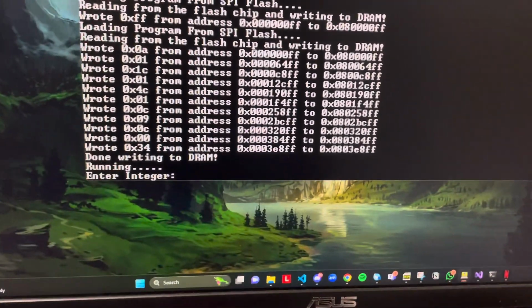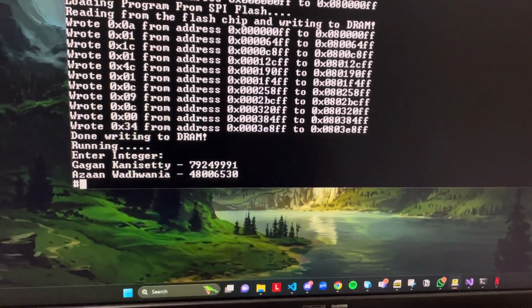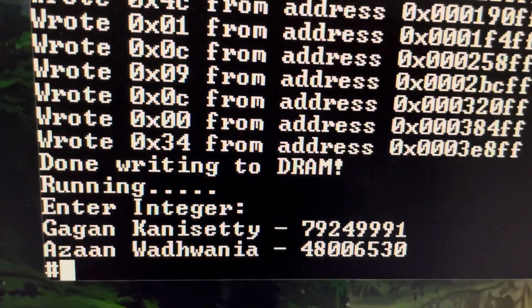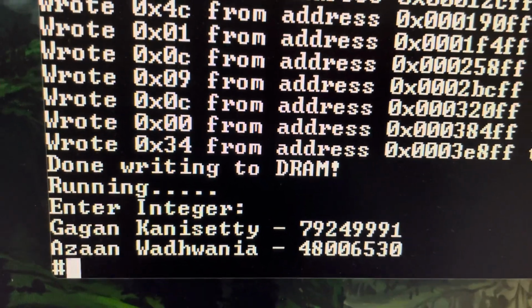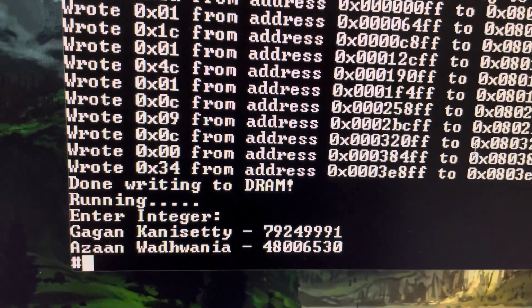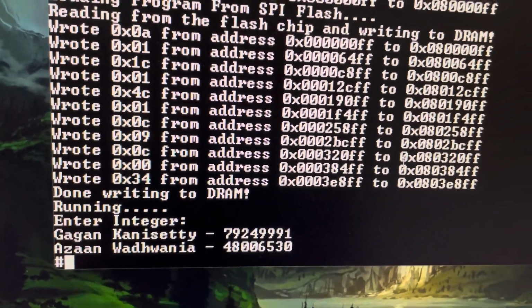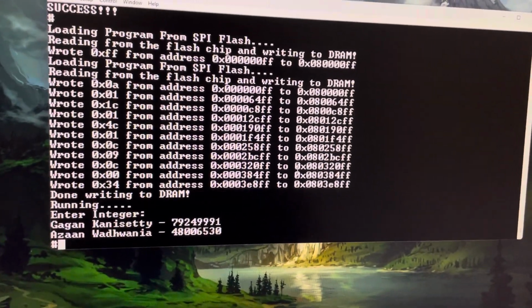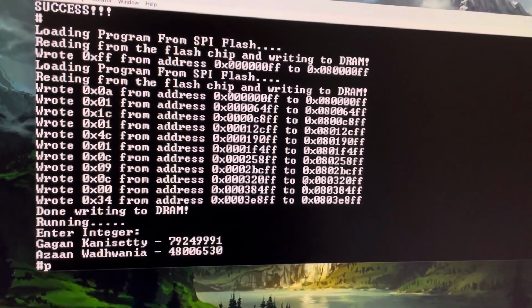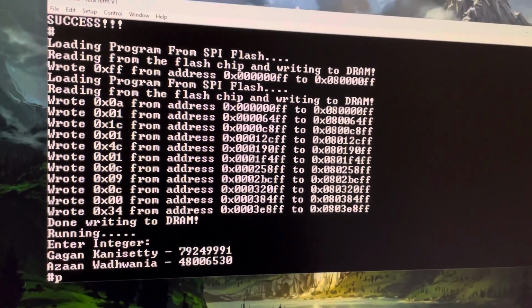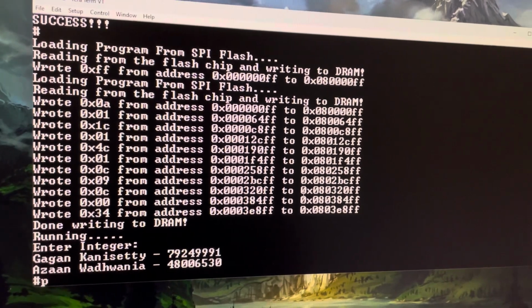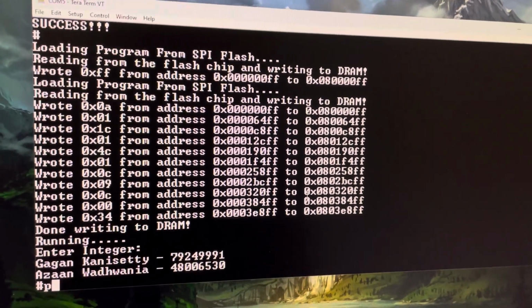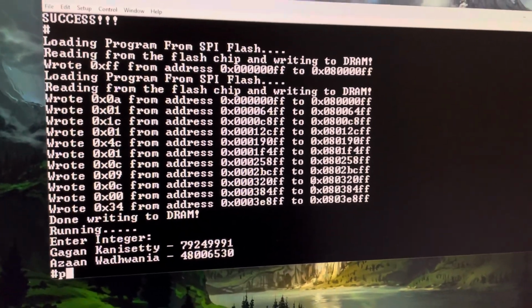And this is the user program, so we can turn off switch 9 and reset. This user program was provided in lab 1, so we just loaded that user program, which was asking us to input integers, and it changed the LCDs accordingly. As one final check, we can again say P, and this should write from the DRAM to the flash chip and then read back the values.